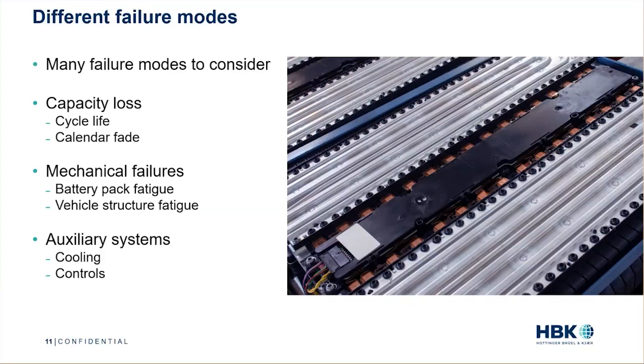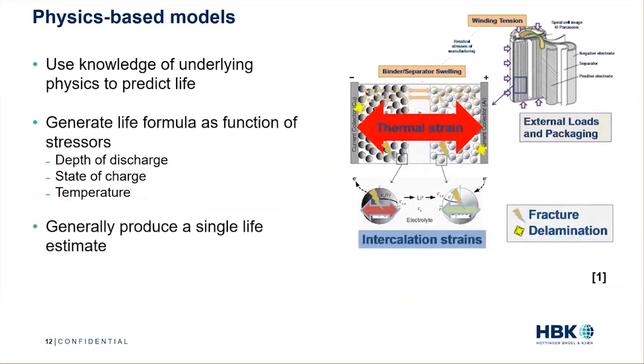So we've got all these different failure modes, and many of them have been or are being carefully studied by people with deep knowledge of the physics of failure here. So the battery chemists, material scientists, physicists, etc. And you could find all kinds of interesting models that predict life as a function of some stressor or some combination of stressors. In the same way that my background's in mechanical engineering, you might predict fatigue based on a combination of stress range, mean stress, surface finish, stress concentration factor, those kinds of things, right? And these models are definitely going to be useful for us.